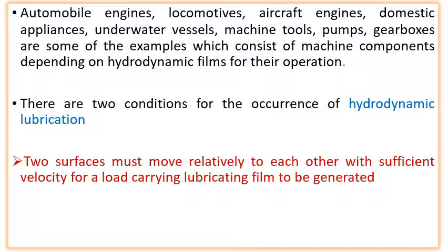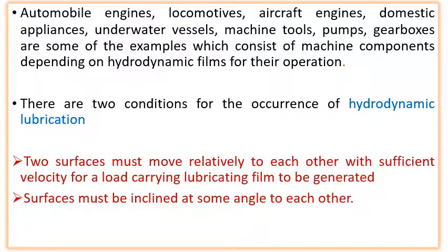One is that the two surfaces must move relative to each other with sufficient velocity in order to generate the pressure to carry the load. And second, they must be at some inclination to each other. They should not be parallel. If they are parallel, then the pressure cannot be built up.